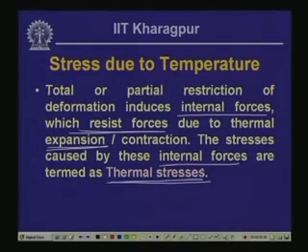If you remember, if you take a body and allow it to undergo a change in temperature, if it is not restricted or constrained, it will move or expand if the temperature rises. But if we do not allow the bar to move freely and we put some restrictions, then the expansion will be restricted and thereby internal force will be induced into the system. The stress that is induced because of these forces, caused by the thermal expansion or the change in temperature, we call thermal stress.